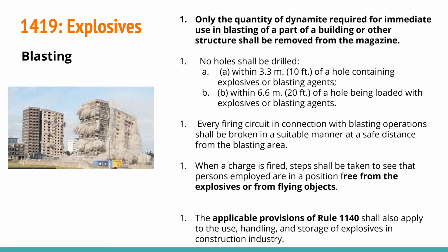Every firing circuit in connection with blasting operations shall be broken in a suitable manner at a safe distance. When a charge is fired, steps shall be taken to see that the persons employed are in a position free from the explosive or from flying objects. Also, lastly, the applicable provisions of Rule 1140 shall also apply to the use, handling, and storage of explosives in the construction industry.